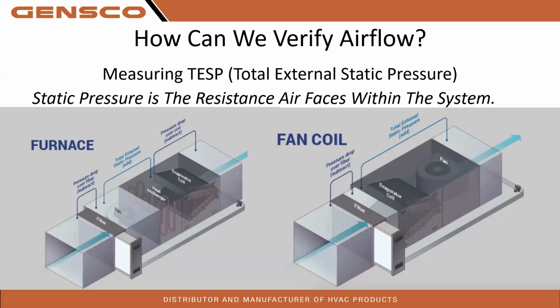If you ever call into tech services, we ask you, please, what is your external static pressure and what is the speed tap on that unit? This is what we are talking about. Total external static pressure. It is the pressure that is the resistance in the airflow, the air places within the system. It's what that blower sees.